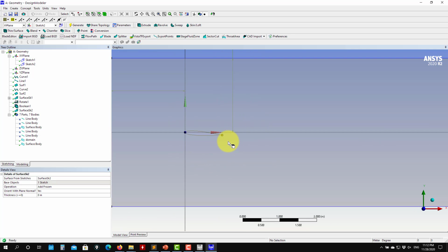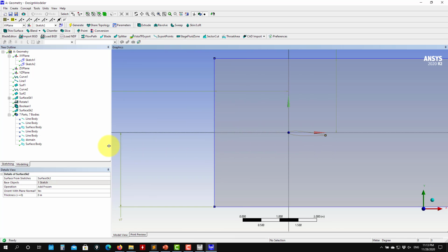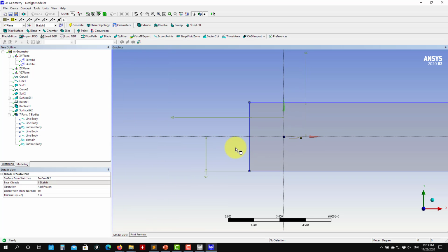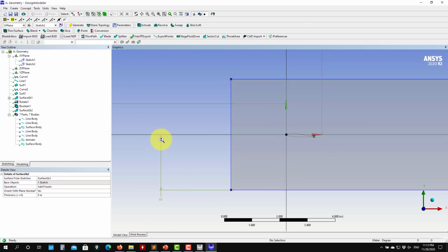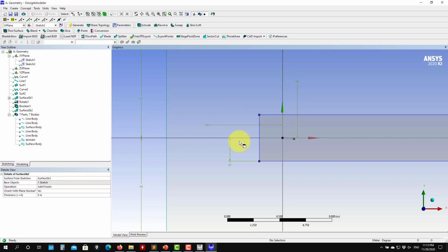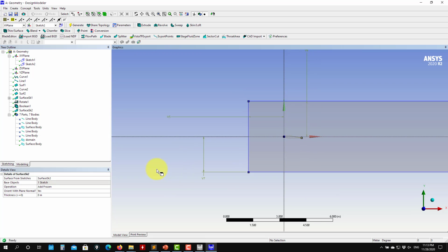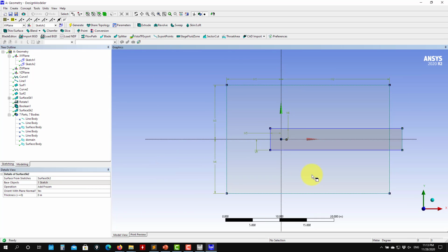One thing also, remember that forces are parallel or perpendicular to the incoming flow. So in this setup that I'm doing, I am rotating the airfoil. So my incoming velocity is always horizontal, in the X direction. But you can also leave the airfoil fixed, and then you can change the incoming velocity. However, this domain is not ideal if you change the incoming velocity, because you need to add boundary conditions here and here.